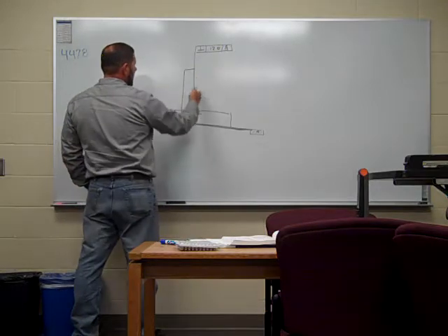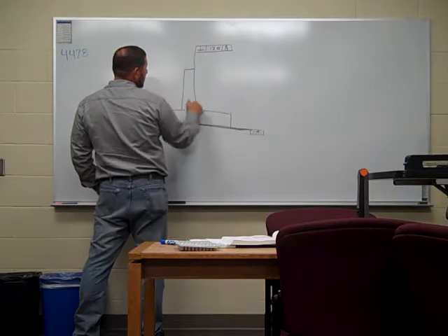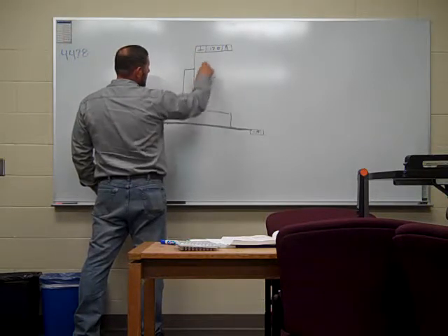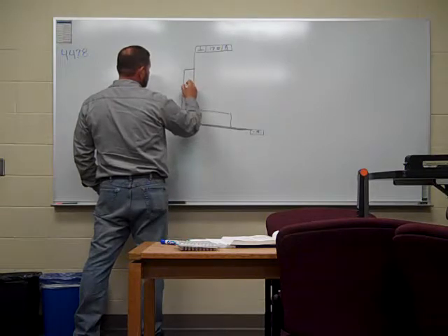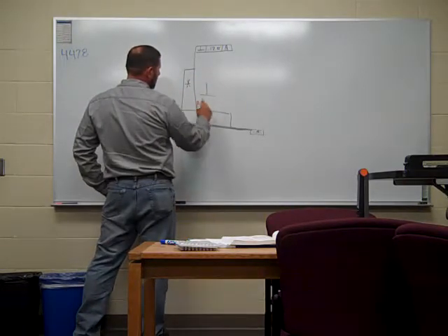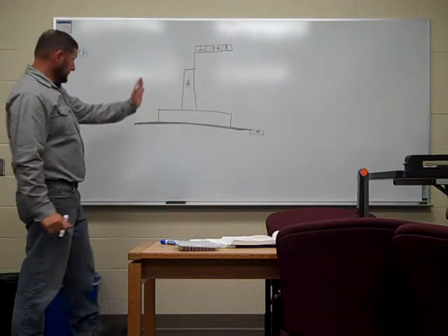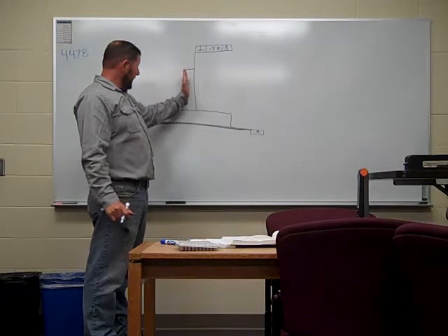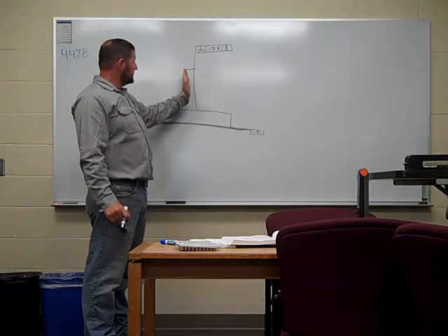This edge right here on this piece, on the vertical T-joint, is going to be perpendicular 1/8 of an inch to datum A. So this piece right here has to be perpendicular to that datum within 1/8 of an inch. As you weld that, it's going to tweak and bend a little bit and twist and all that good stuff.